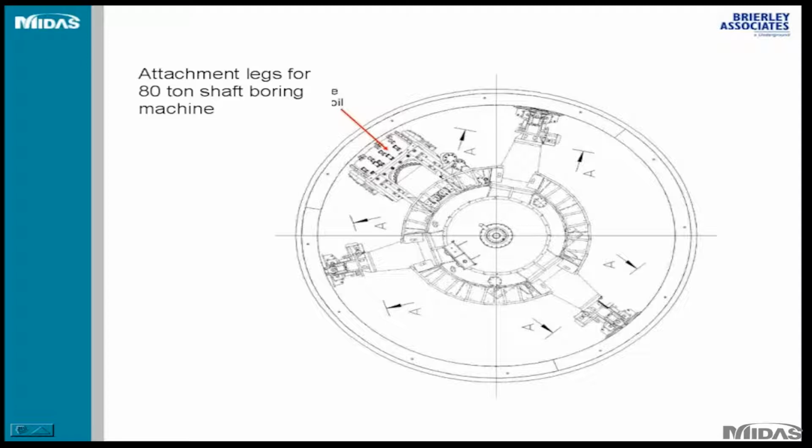You advance it one ring at a time. Each ring was about 1 meter high, which is about 3.28 feet. Each time you let it sink and advance it slowly, basically. But yes, the jacks and strands can suspend the whole shaft in place if needed. And that's what you design the ring beam and everything for, and that's how you rate your cranes or the winches and the jacks.